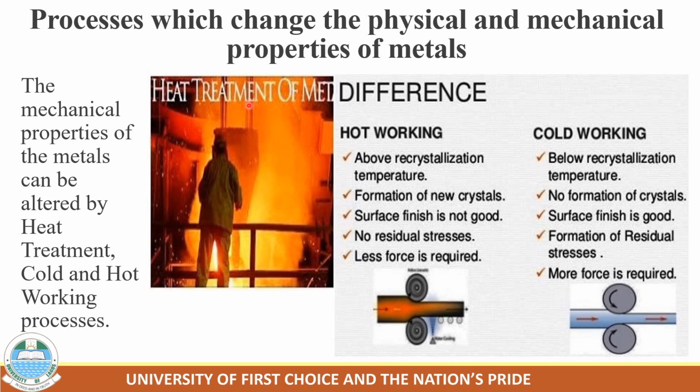So that material, again, you put into the forge or into a furnace. Let that material be heated to Austenite temperature. When the material is heated to Austenite temperature, it gives the microstructure inside the material the opportunity to move around easily. They will be free to move around easily.